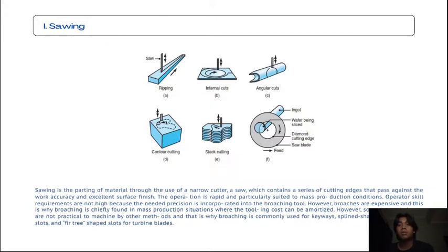The equipment required for broaching ranges from simple arbor presses for keyway broaching to huge special machines used in the automotive industry for surface machining engine blocks and other large components. Holes as small as 1.3 mm and surfaces as large as 0.5 m wide can be broached, with continuous or reciprocating motion.